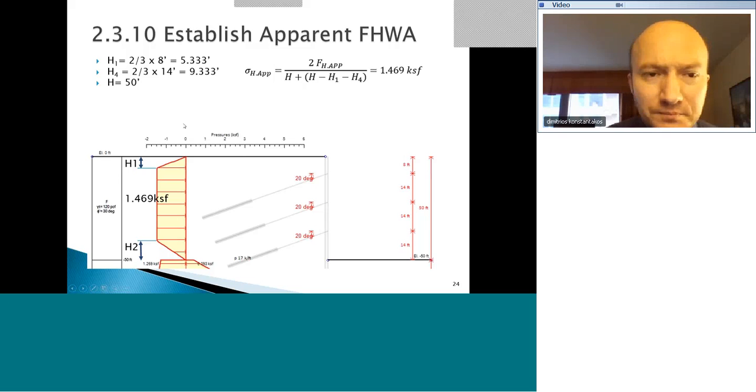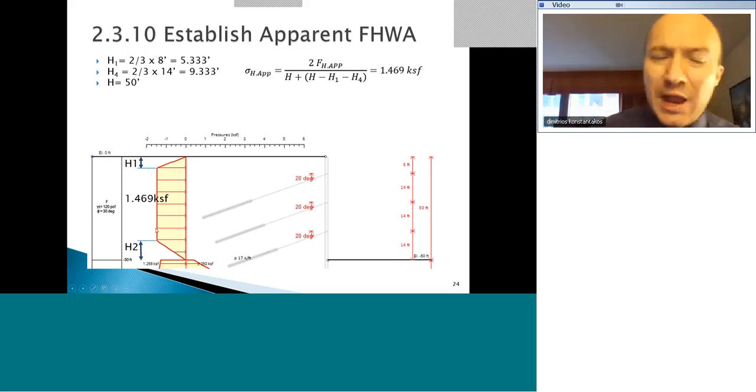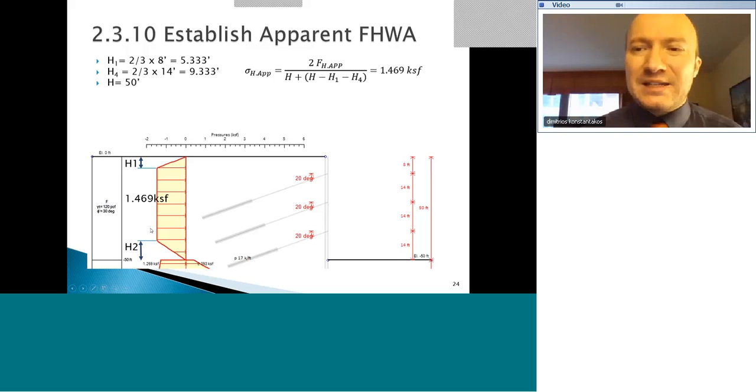So the idea is that we're calculating the apparent earth pressures here. We're coming back with the apparent earth pressure diagram. Now, one of the things with these diagrams is that in some cases, they don't distinguish between what's happening above your water table and below your water table. We're actually putting forward some recommendations on how this can be handled. There's also some other recommendations around.